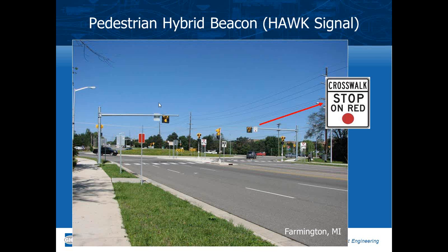In the end, the agency decided to leave these in, and now they put in underground on most of the 2-lane roundabouts in the event that they get a request to install. They have the hand wells and ducts, the conduits underneath the pavement, so they can place them if they are warranted or if a request is made and an engineering study proves them to be necessary.